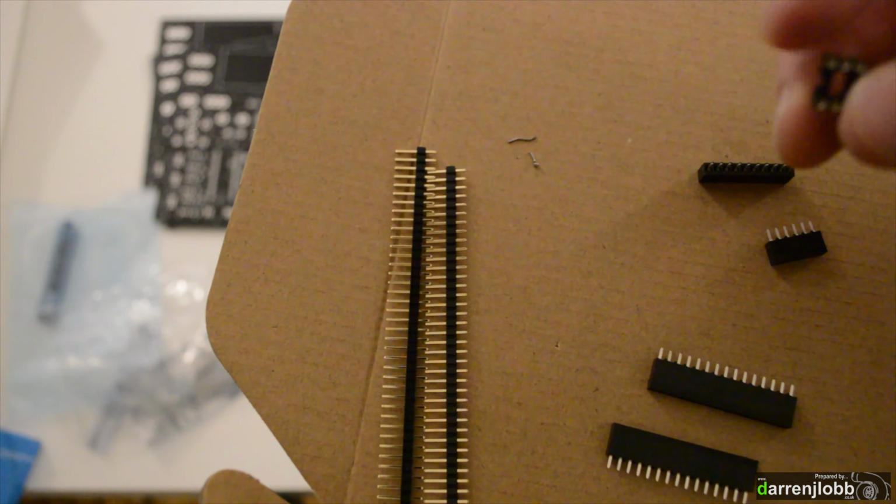So this end of the board, we've got power in on the left hand side there, and then your wires going out to either your steering motor or your hydraulic valves on the far side there, and then you've got your pins here that interface with the rest of the board. You can actually see on the bottom of the board those connections are marked, so you can't really go too far wrong. So you've got motor on the left there and power on the right.